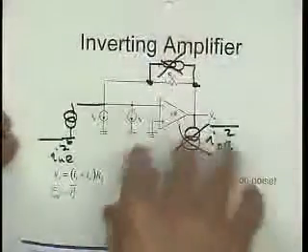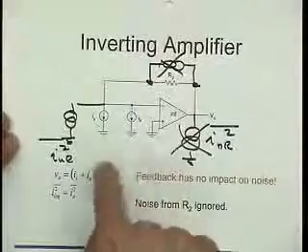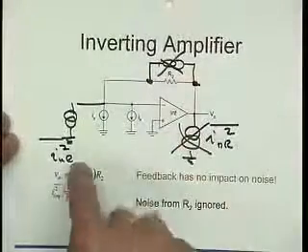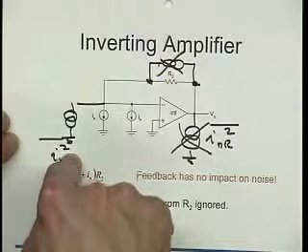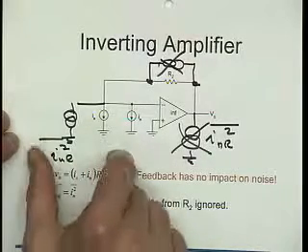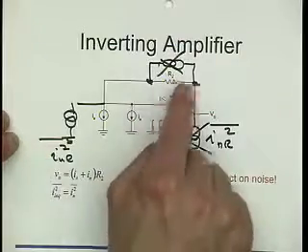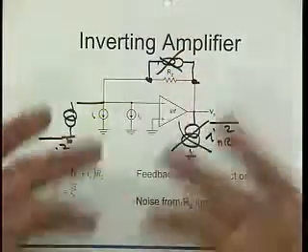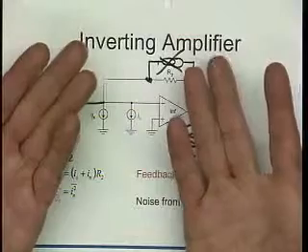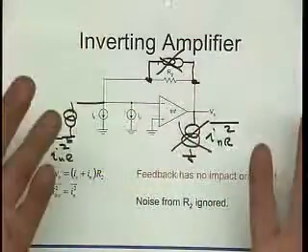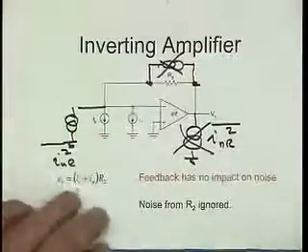Anyway, so here also, obviously, if you had calculated this with voltage noise and done all the calculation, then got an equation for the input referred noise, you would have seen from the format of the input referred current noise that it's really just a noise from that resistor. Then, if you see something like that, go back, look at the circuit and see whether you can find a way to more quickly calculate it, like what we just looked at, right? Okay.